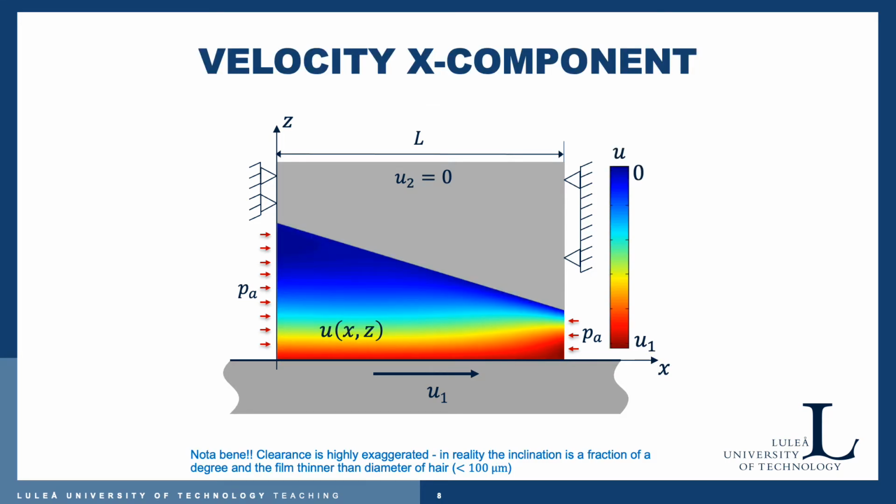When we talked about the lubricant rheology previously, we already saw the X velocity depicted like this color map. But what is interesting to notice here is that there is a region of backflow in the trailing edge of the bearing. It's not so easily seen at the color scale for the velocity that we have here on the right.